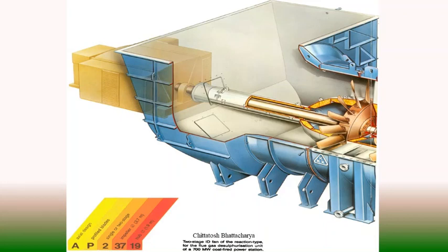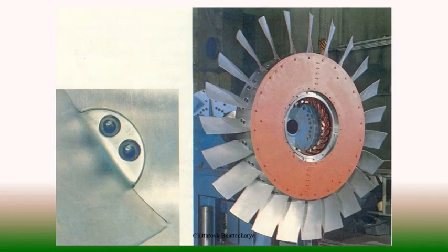and we also have some shaft protecting devices. We have a tube covering at the inlet ducting of the suction, so that if there is a flow of dust-laden gas, the shaft is not getting damaged. There are stiffeners to support the casing, because there is a change in direction in axial flow fans. Suction is axial and discharge is also axial. So naturally there are some directional vanes also, and a horizontal splitting arrangement is there to prevent eddy formation in the flow passage.